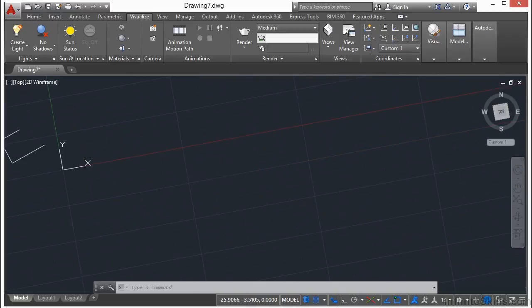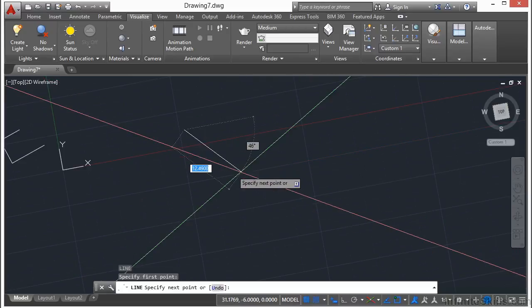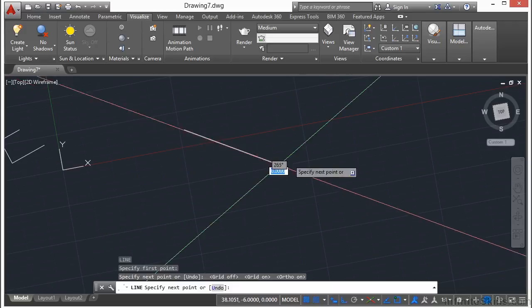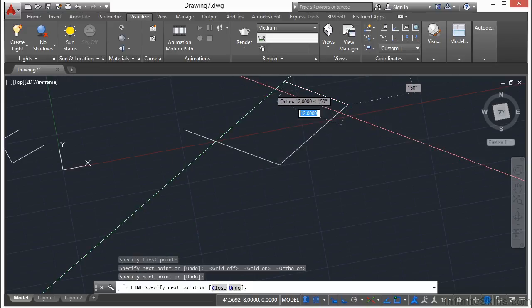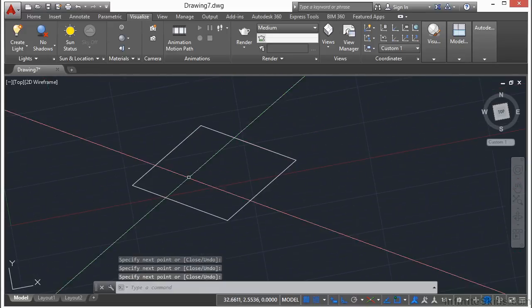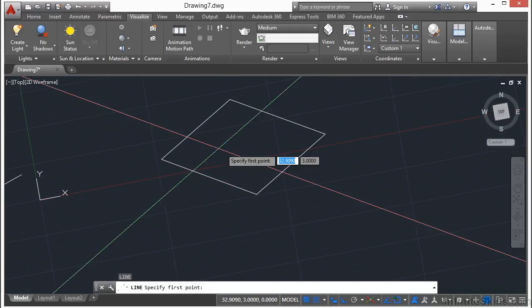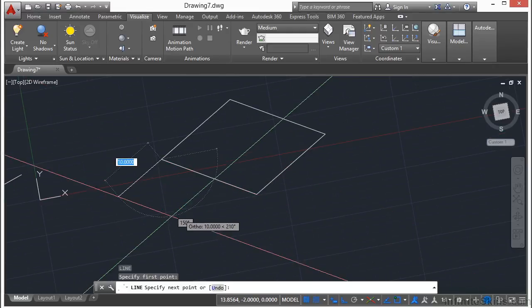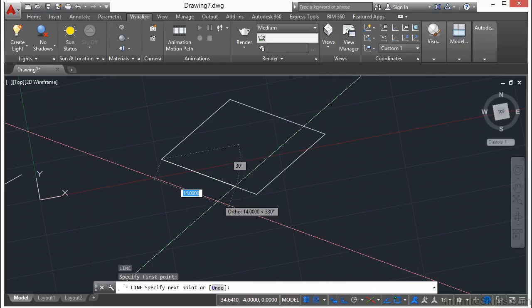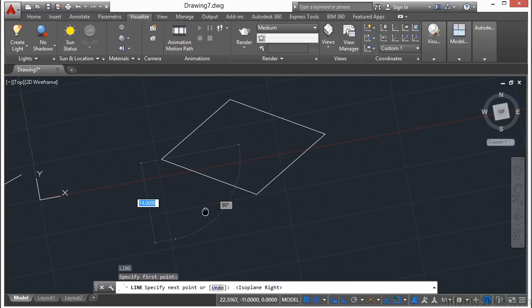So let's start drawing. If I draw here and I turn on F8, this will lock me into isometric mode so that I can now draw 3D isometric set of line works. So I can kind of draw an isometric view of a cube. So I can come down here and I can press F5 to toggle through my different isometric planes.